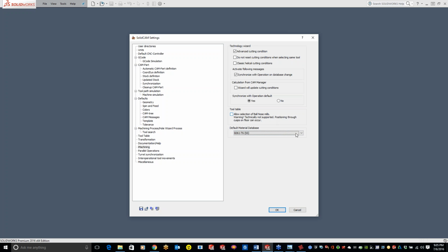Inside here, you guys will notice that iron machining, or basically 3D iron machining, does not support ball nose end mills. It does work, but you want to always solid verify just to make sure. So if you guys want to be able to use it, just turn this on, and that will allow you guys to pick ball end mills when you use 3D iron machining to rough out your part. It's not ideal just because a ball end mill doesn't have a lot of surface contact area, but if you guys want to use it, just come here and turn it on.